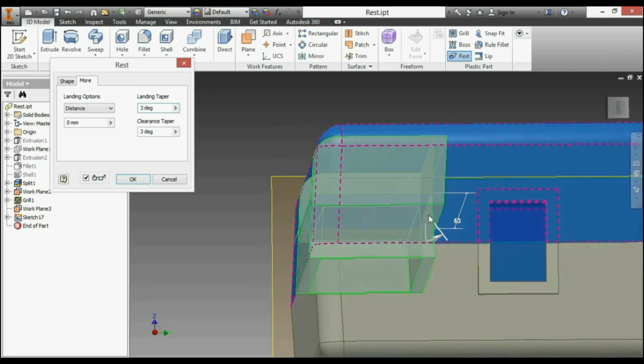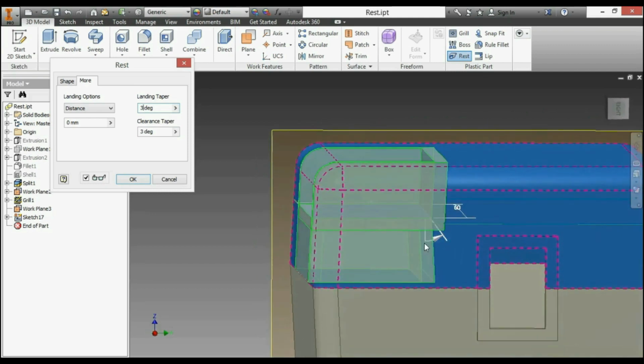However, on the back side, you can see that it is bowing out a little bit. And maybe I need that. You know, if this is going to be pulled off of a plastic part design for injection molding, I might need that draft on there.